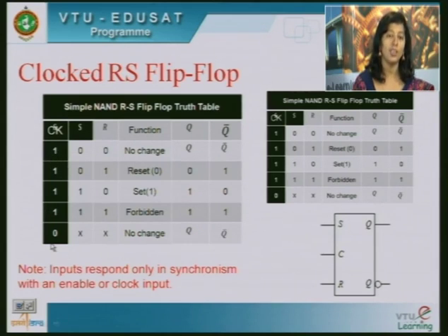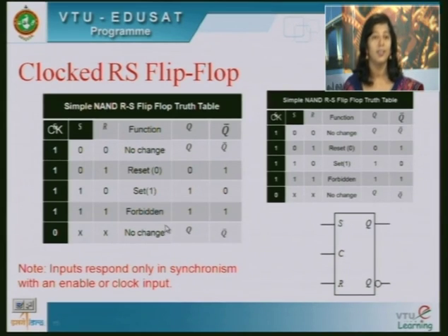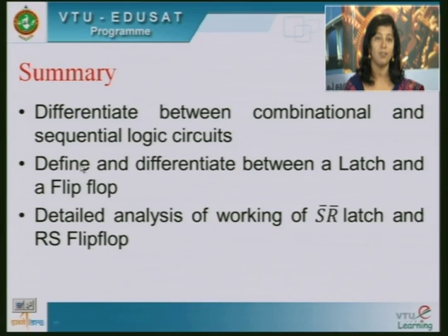If the clock is 0, then irrespective of S and R, the output will remain in the no change state or the previous state. That means the complete flip flop or latch is disabled. So, output will always remain in the previous state or the no change state. So, inputs respond only in synchronism with an enable or clock signal. This is what a clocked RS flip flop is.